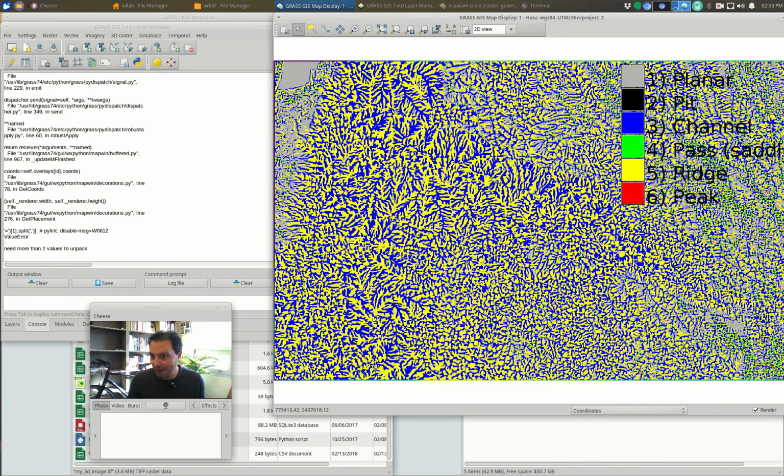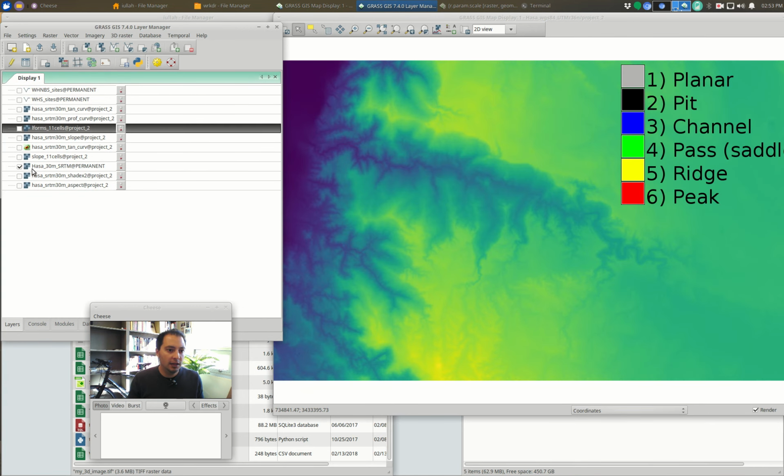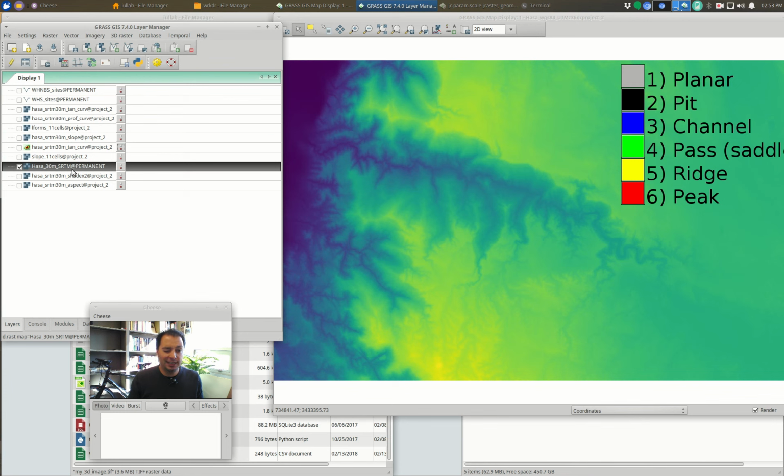Anyway, sorry about that. But basically you can see it's showing us our key over here. So let's go back over here. Let's again only show this. So the key here, when we're going to 3D, whatever layers are visible, it's over here with the checkbox. It's going to try to render in 3D. It's going to read the number inside the cell and assume that that's elevation. So if the number is a category, it's not going to be meaningful in 3D.